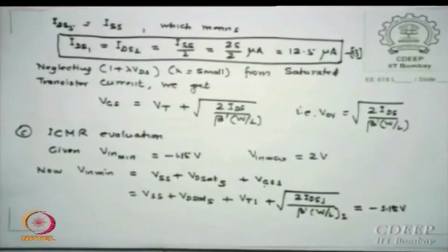So these max and min words are not really the actual max. The max word was given from calculation from the uppermost values, the VDD value down and the VSS value up. So this confusion should not happen, that you are not meeting specs, when actually you are improving the specs. What are common mode ranges we are saying? We are trying to say that in this input swing the transistor remains in saturation. Is that clear? That is the range I have given you.